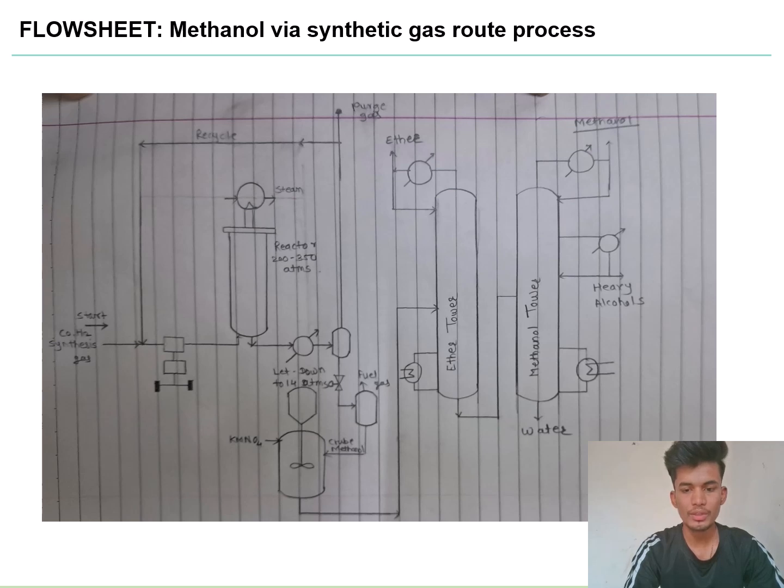The raw materials, which are carbon monoxide and hydrogen gas, are sent to the catalyst for the reaction, and there carbon monoxide and hydrogen gas react to each other to form methanol. In the reactor, temperature is maintained. Also, the reactor exit gases are cooled by heat exchanger with reactants and with water. The unreacted exit gases are recycled or purged to maintain molar ratio.